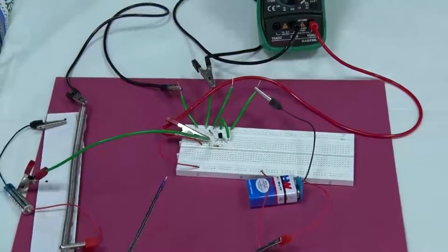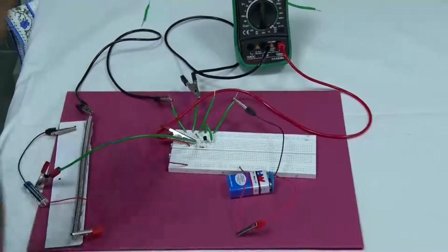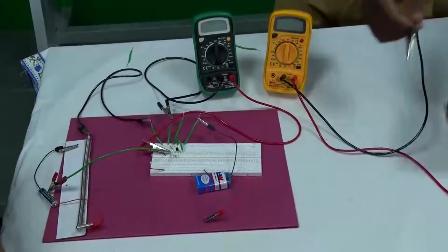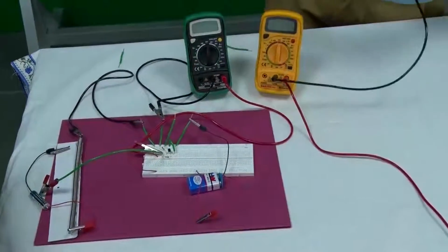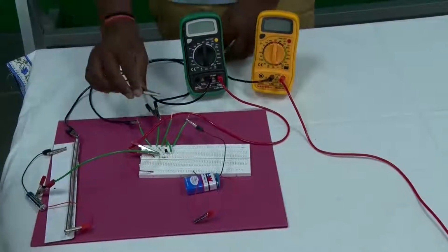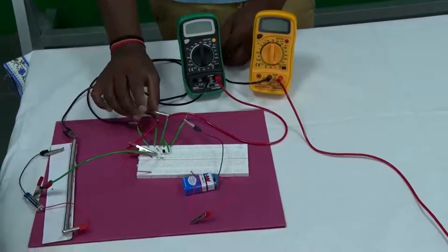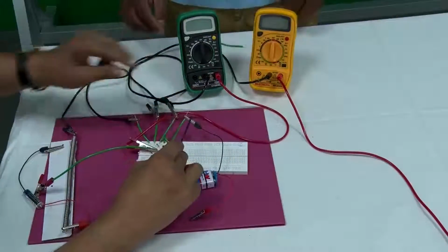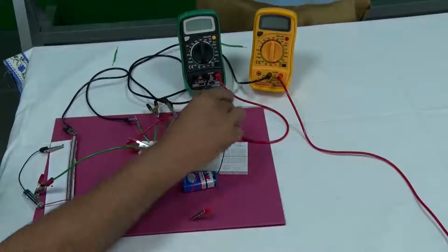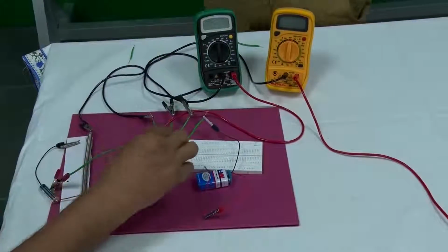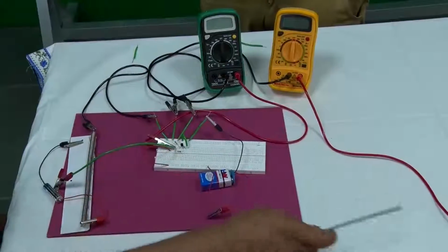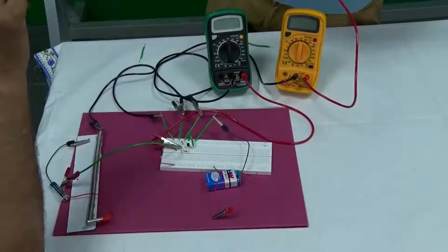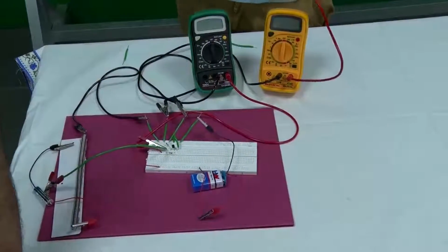Then the output side. In the output side, once again the black terminal should be grounded, 0 potential. So, see how the circuit is implemented nicely. This is also at the same potential. All those negative terminals, all those black leads, are joined together. And the positive red terminal should be measuring VO, the collector, so it has to be directly connected to the collector.